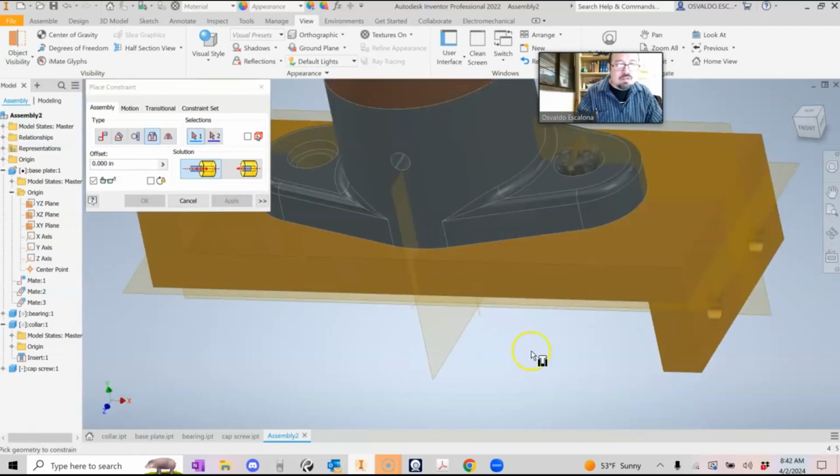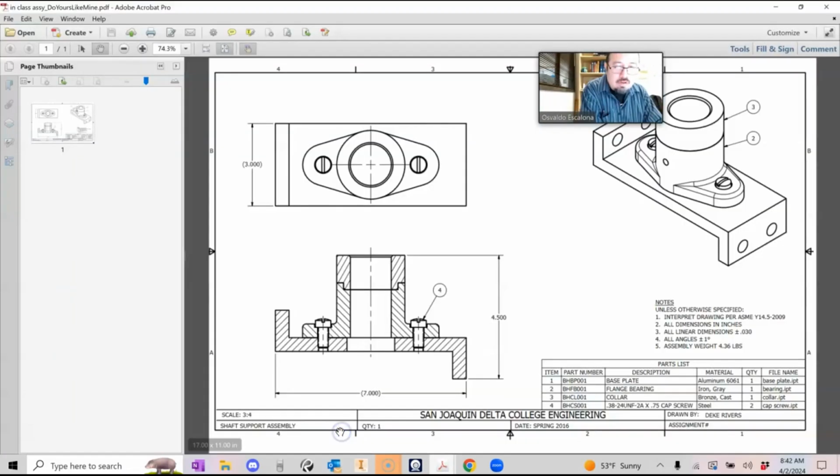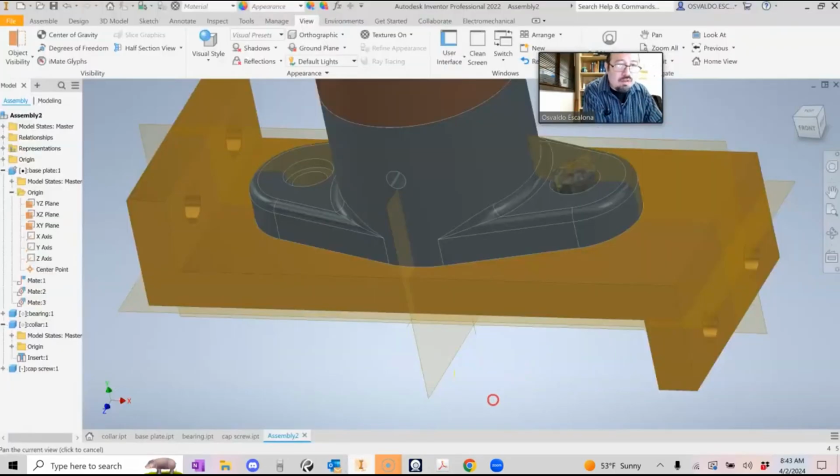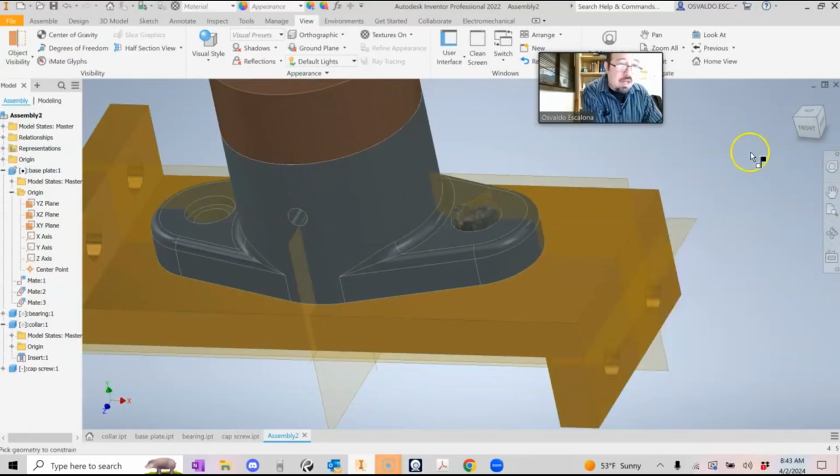And I also want to constrain the rotation of my bolt, because if I want to rotate, you see it rotates. So I need to put an angle. So if I go here, you guys will notice that my bolt, the flat head, is aligned to my axis. So I am going to try to constrain it, but now I'm going to be using an angular constraint.